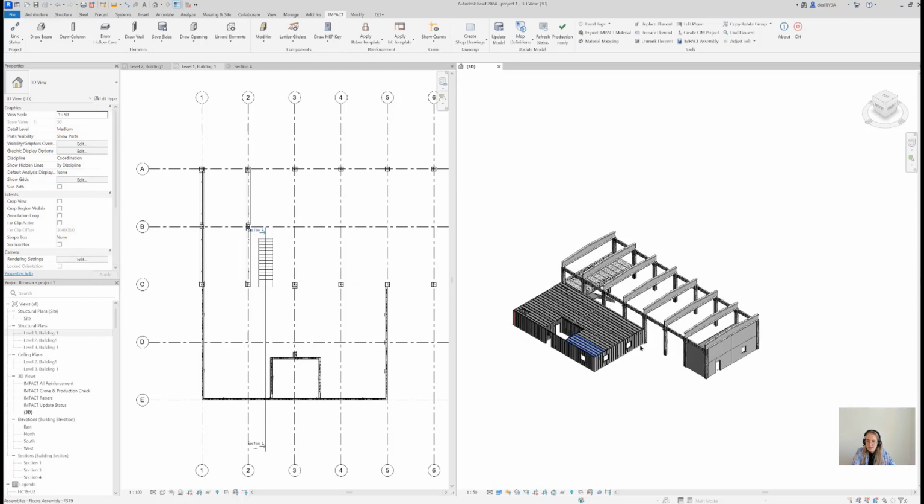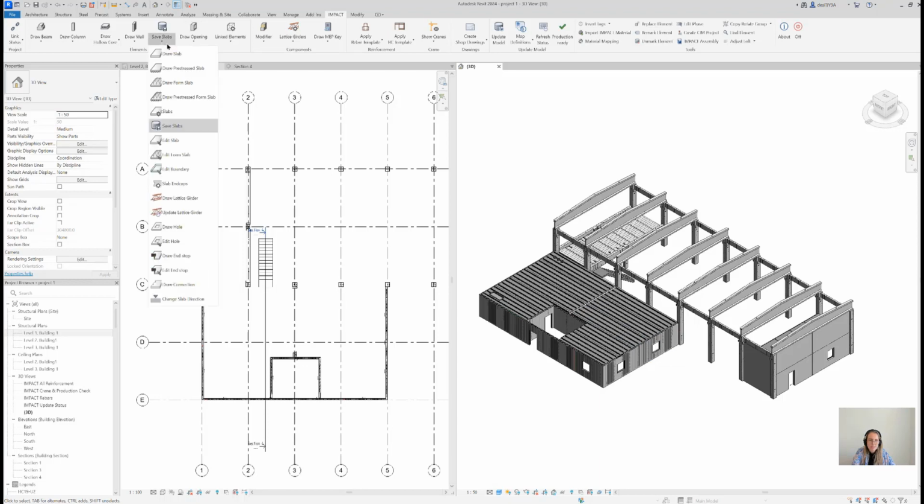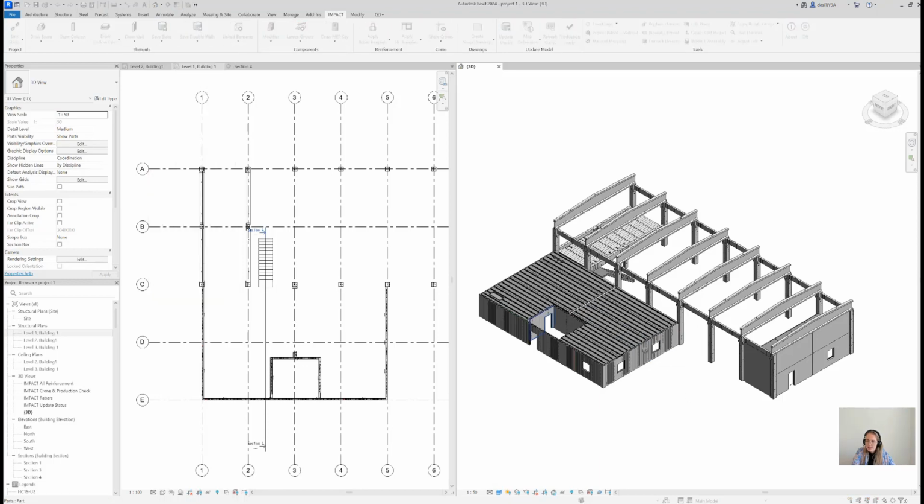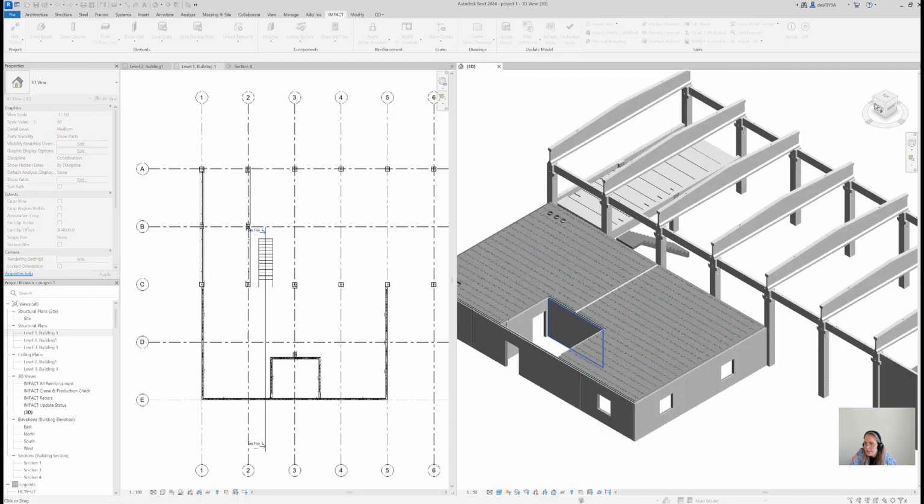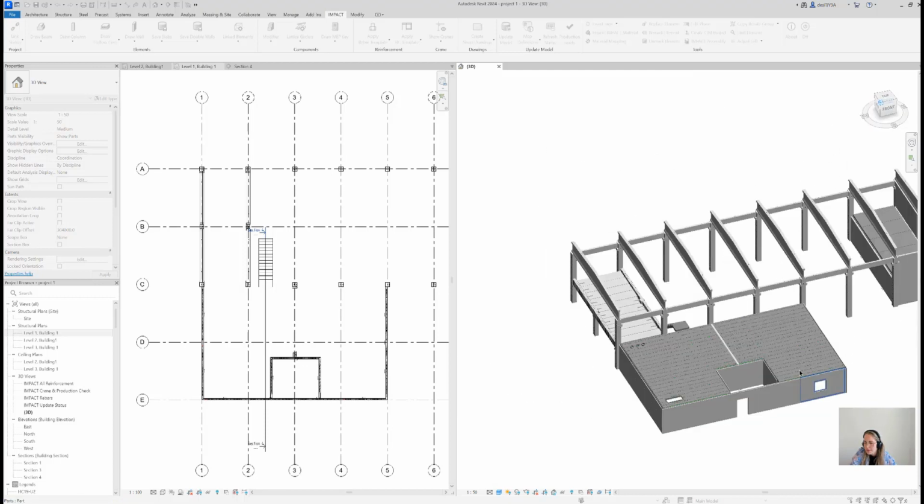And now we go and save the double walls. We have a save double wall command, and I use the 3D as for me it's easiest to orientate. What you can also do is cross select. It's also easy, probably less time consuming. Go this way. Then I can do here.